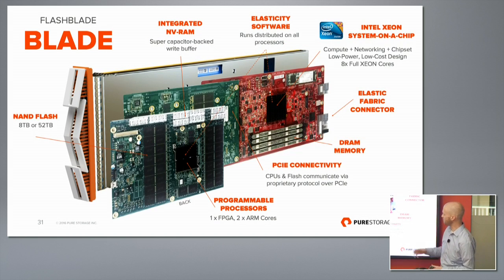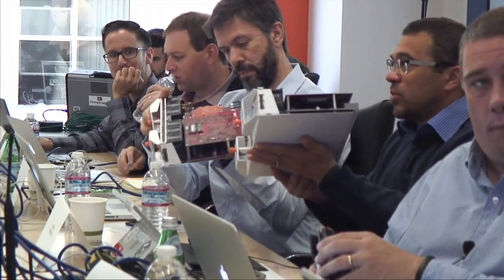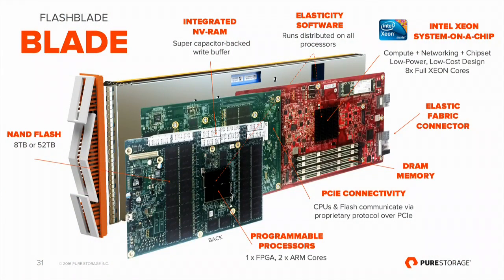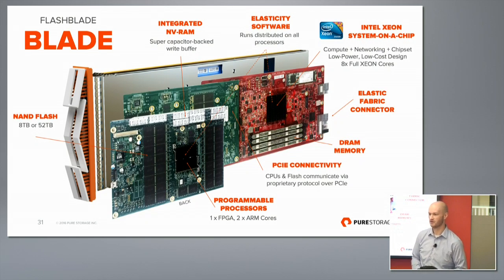And then pictorially, and I think you can find pictures of this online as well, this is kind of the same walkthrough. There's the storage module, the FPGA controller and flash, DRAM, supercapacitors. You're asking about the amount of NVRAM we put. The original prototype that Chris is holding only has 2 of the supercaps, and the boards here have a lot more. The reason for that is we did experiments and found just how beneficial it was for performance to have more NVRAM. More NVRAM needs more hold-up time, so we put more supercaps down, all through experimentation.